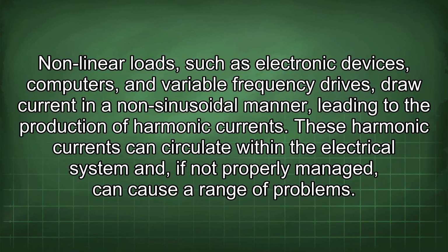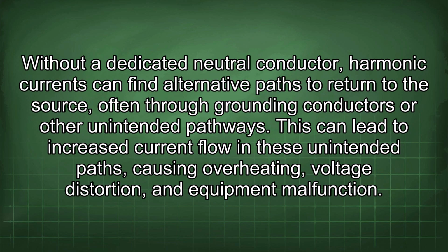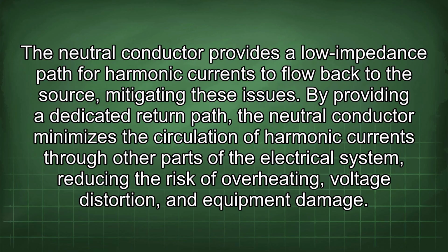a range of problems. Without a dedicated neutral conductor, harmonic currents can find alternative paths to return to the source, often through grounding conductors or other unintended pathways. This can lead to increased current flow in these unintended paths, causing overheating, voltage distortion, and equipment malfunction. The neutral conductor provides a low impedance path for harmonic currents to flow back to the source, mitigating these issues.